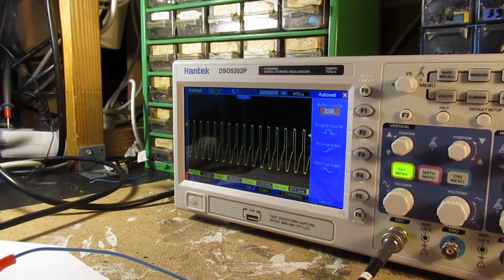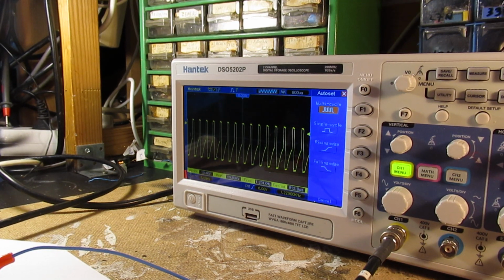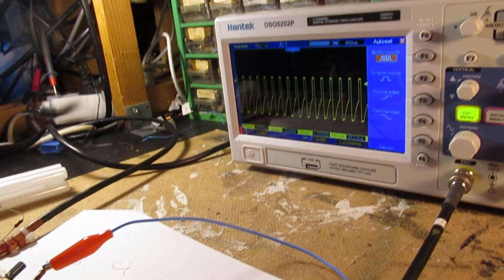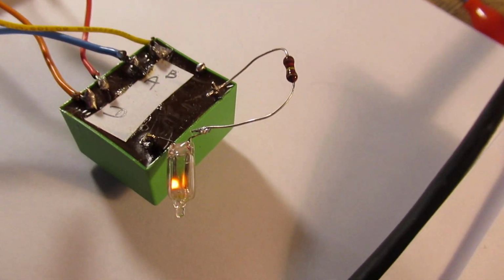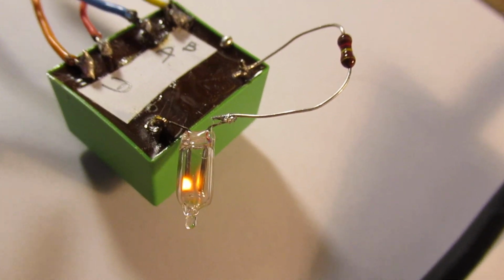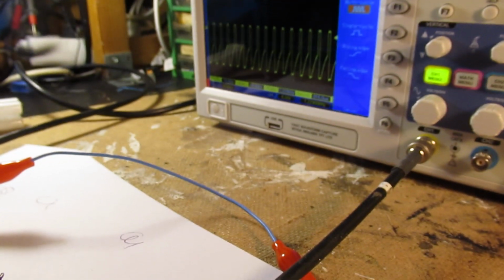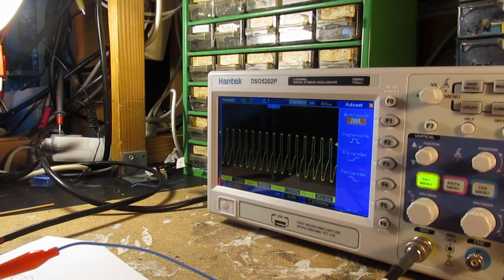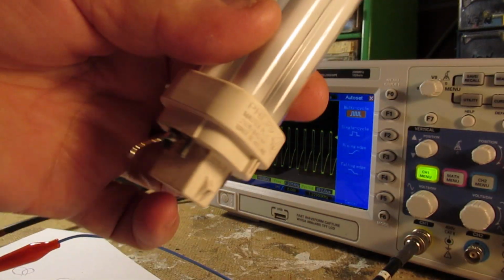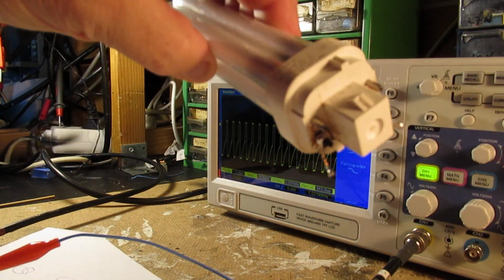it's always very important to say, when you want to find the high voltage on the secondary side, use a small neon tube. Often they are mounted into screwdrivers. You can also use this here, a spare lamp tube.